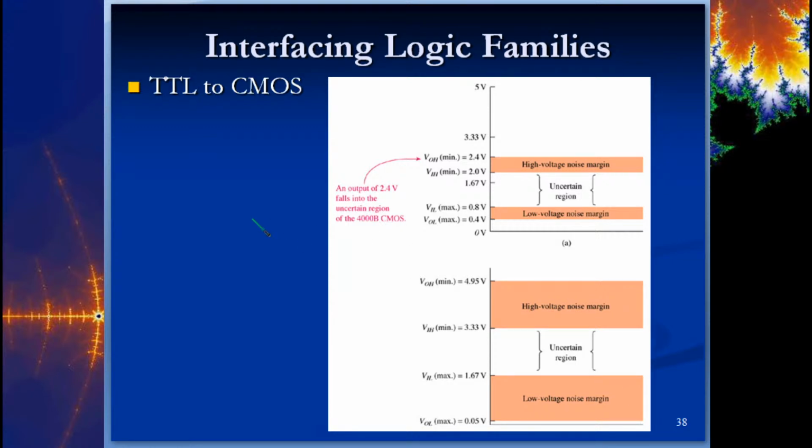So, just to reiterate what you couldn't see, there are essentially two different regions here for each type, for the TTL and for the CMOS. So this is what I was referencing. You can see that up here for a TTL, if we were going from TTL to CMOS, the output high minimum is 2.4. So my test case was, okay, let's say I have a high out of a TTL at 2.5 volts. Look at what the input high minimum is on a CMOS.